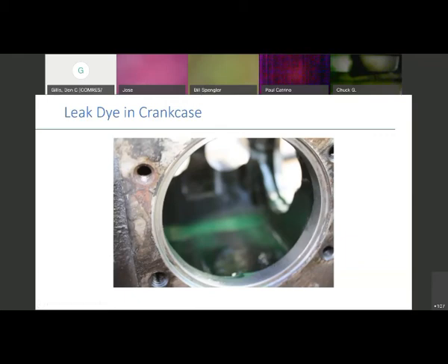Obviously, when we get dye in there, you know how PT charts work. We can check the PT charts up against a recovery tank. You know how that works, as long as we have vapor and liquid. Well, you can imagine how that's throwing that off if you start putting so much dye. And even in the short time I've been here, I've seen it to where we've poured refrigerant out of these compressors that's come back to where it fills up a 5-gallon bucket or about a third of the way up, and it looks like radiator fluid. It's really, really bad out there. I'm sure the folks that are in the wholesale business understand that better than I do.